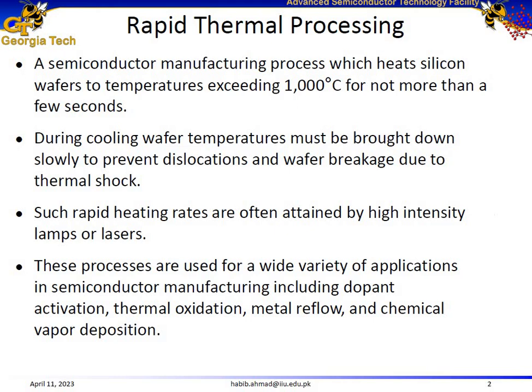Otherwise, there is a chance of wafer breakage, of breaking the semiconductor samples due to thermal shock. And actually, in my previous lab, this has happened: sometimes the students would anneal the samples and then they would ramp down the temperature in a faster way. They would cool them down rapidly, and during this process they would break the samples. So this is the only care that must be taken, that the cooling process must occur in a slow manner.